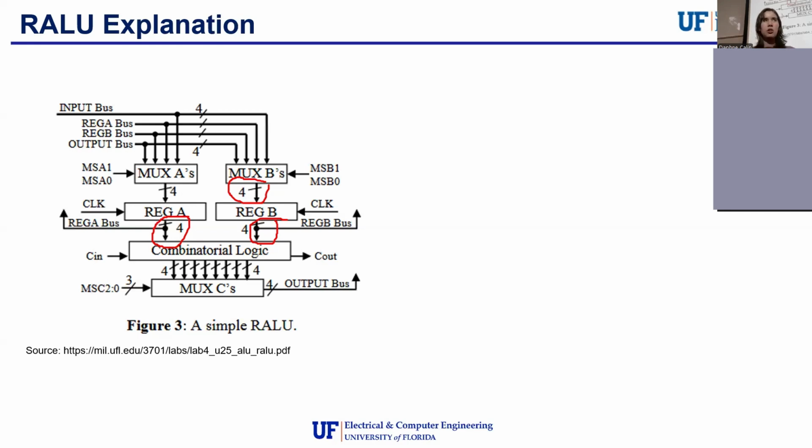D10. What you can do is something that I saw in Lab 7. You're given a Quartus project and it has two BDFs in it. One of them is for simulation, one of them is for programming. Something you might want to try just for the sake of programming on your board is making a separate BDF and removing some of the extraneous output pins from that BDF.